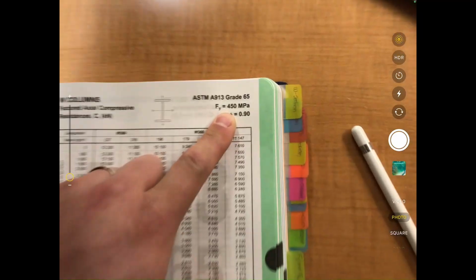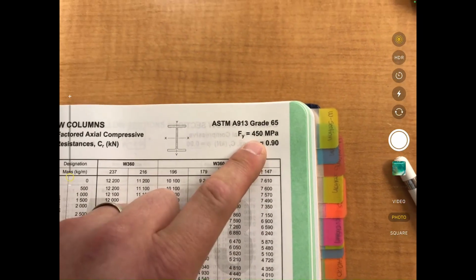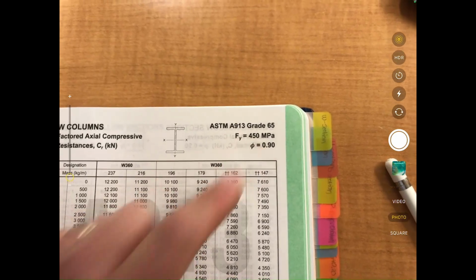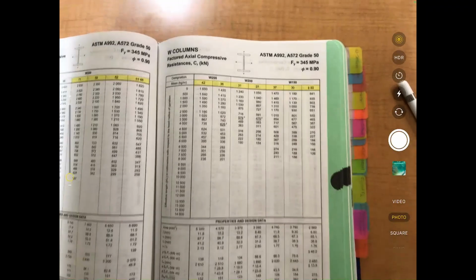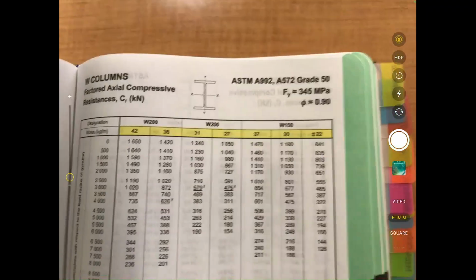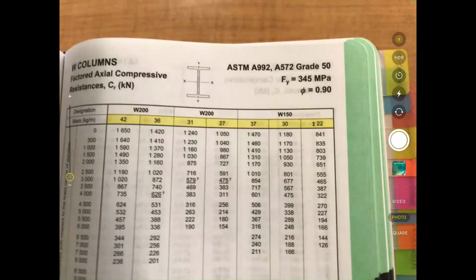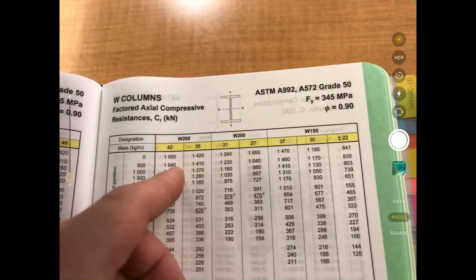It's becoming a little bit more common to use higher strength steels, but in our 345 or grade 50 steel, we want to make sure that we're not unduly requiring the steel fabricator to procure some A913 structural steels. Okay, the first page of wide flange sections, that's grade 50, right? We can see there, grade 50, 345 MPa. And we've got the smallest sections available to us to start, W250, W200.